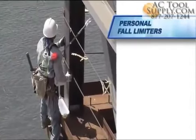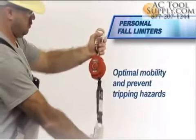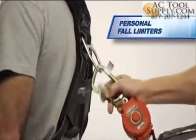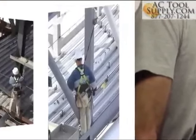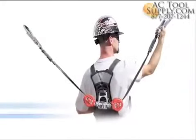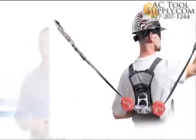Personal fall limiters are lightweight web connectors that require less fall clearance and offer optimal mobility while preventing tripping hazards. They may be attached directly to the back D-ring or used as a traditional retractable lifeline. Double leg units are also available for 100% tie-off fall protection.